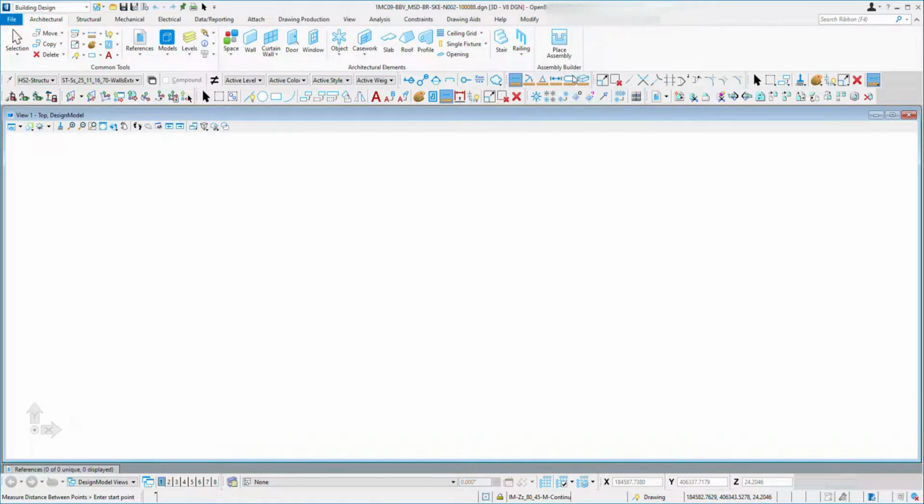Maximum between doesn't matter, and I don't think anyone is using it. Generally we use minimum between. We use it to measure a clearance. Suppose we have a road under the bridge and we want the clearance of the bridge; at that time we can use this command.